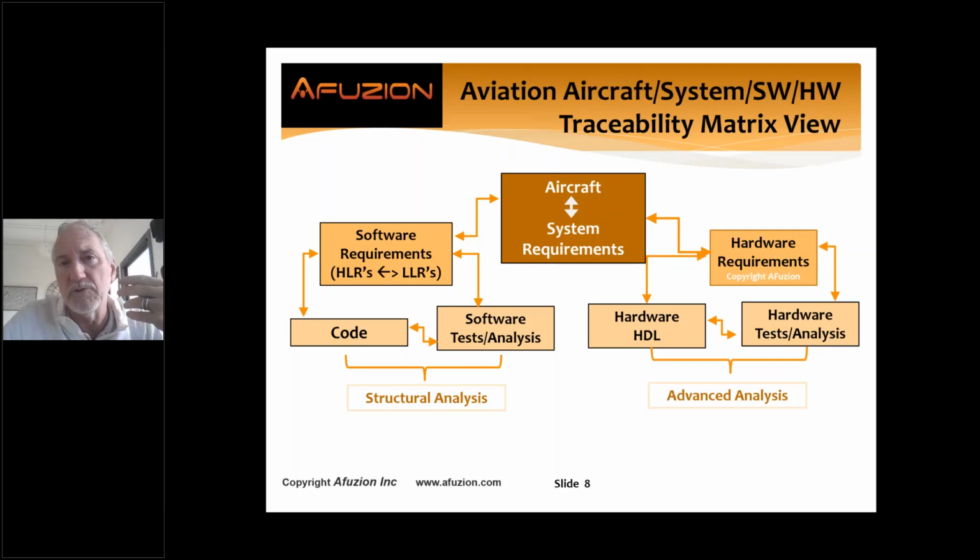If people can be injured, Level C; die, Level B; potential plane crash, Level A. Similar for hardware, except the advanced analysis covers hardware design, logic, HDL, Verilog, VHDL, but only for level A, B, but bidirectional as well.